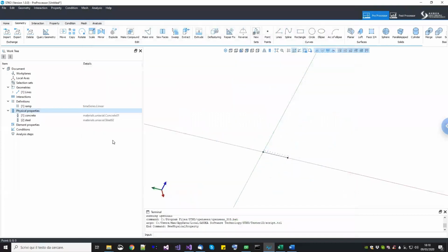Okay, perfect. So we have the steel, and now we can create the fiber cross section. Here we will be using the same fiber cross section we used in the columns of the previous model, the previous webinar. Because in this webinar, we will focus on applying the lumped plasticity only on columns. Of course, you can do the same for beams, but since we don't have much time, we will focus on the columns, which, by the way, are those that carry the nonlinearity of the model.